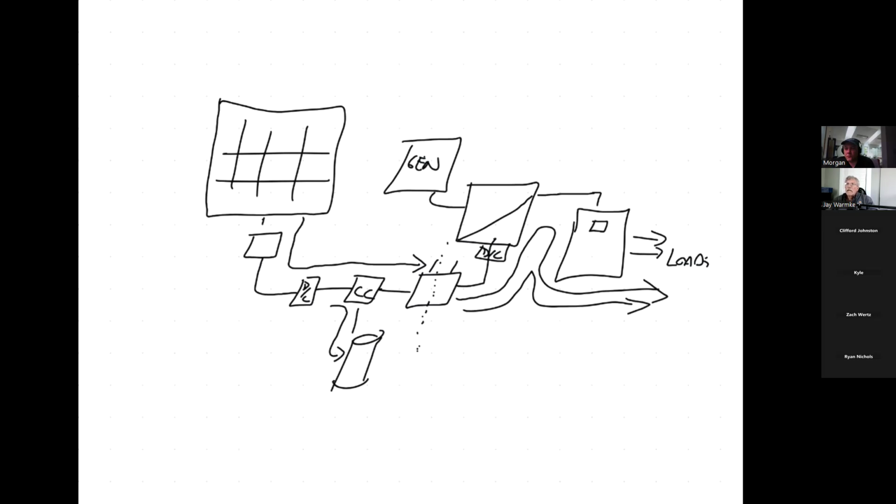So how do I size the inverter? The inverter size is based on the maximum loads I might run at any one time, which is called the maximum power draw. When I size my inverter, I take my maximum power draw, and because you don't want to run your car at full speed all the time, you need to give it a little bit of excess capacity. We usually multiply the maximum power draw by about 1.25. Give yourself a little bit of an overage.